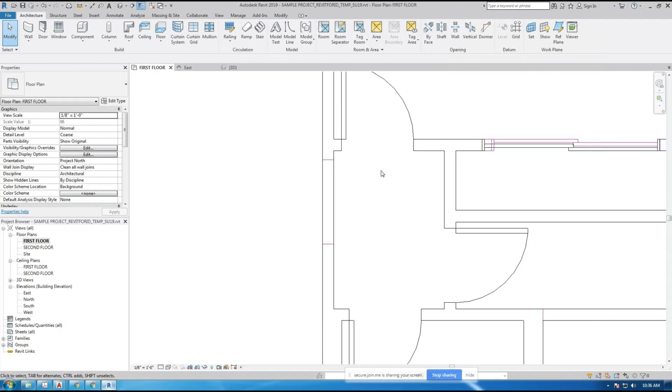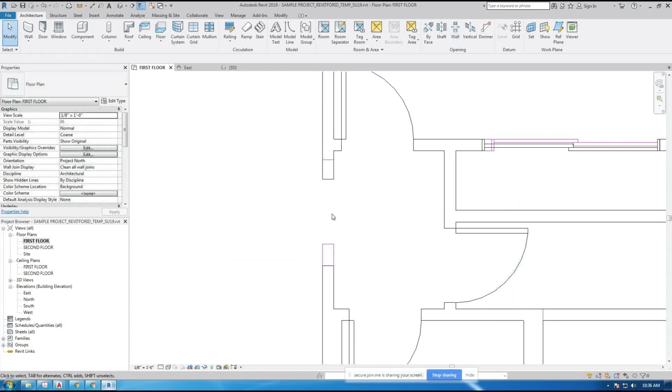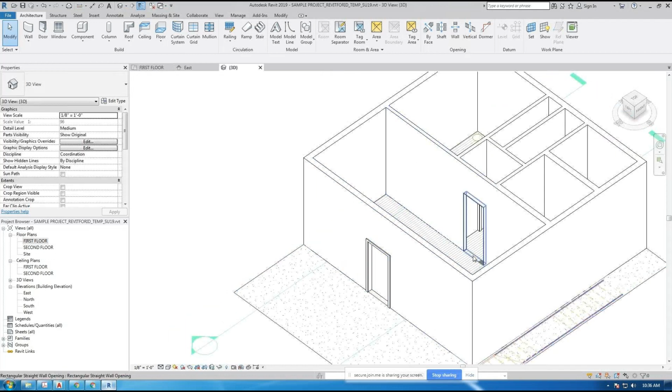So chances are, this is the command you want to use. So how big is this opening? Well, it doesn't really matter. Under the wall command, Opening, let's click on this. It lets me click on the wall that's going to get an opening. Click. Then you use the little rectangle command and draw a rectangle in the wall from one point to the next point. Start here and drag it to here. And that makes an opening, which becomes an invisible 3D model that cuts through your walls right there.